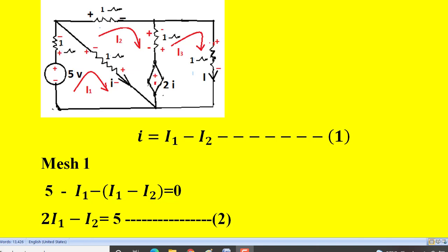So in the assumed current direction I3 or I2, first we are getting the positive terminal here, next negative. So going from positive to negative, we call that a voltage drop. So we write minus 2I. Next,